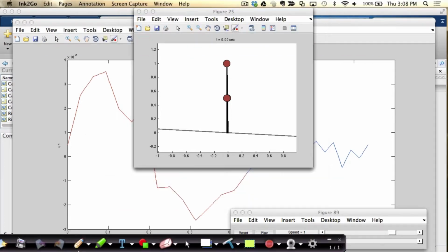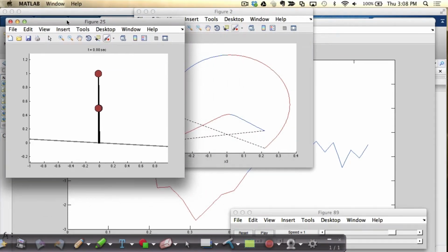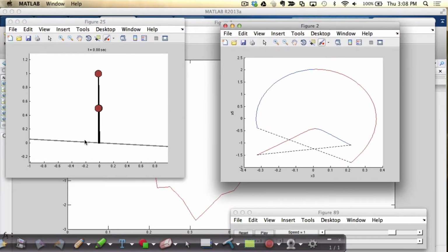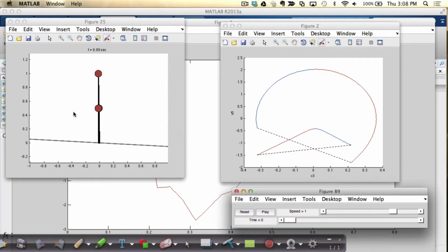That's not what I was going for, but that'll work. Okay, to find the solution that is going to take exactly one step, a periodic solution of this slightly more complicated walking system. Now this one, you'll recognize. This down here is the stance leg. That's theta versus theta dot of the stance leg. It looks just like an upside down rimless wheel. Yeah, this is the swing leg.